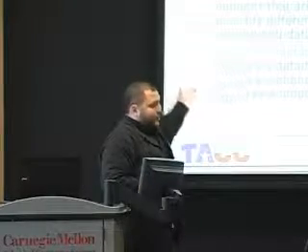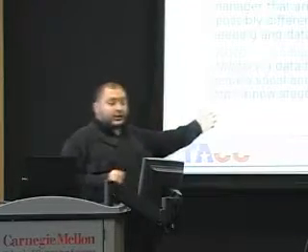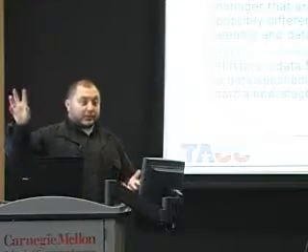The last thing you need is a way of getting data from the field to your actual simulation. That's why we use a sensors-to-simulations framework that we developed back in 2007. Essentially, think of it as sensors streaming data to a data spool, which is, in our case, a MySQL database, using ProdML, the production markup language, which is standard for the oil industry. And we query the actual production data whenever we can from the Ensemble Kalman Filter. And more on that later. So these are the tools that we had to develop to be able to do this.